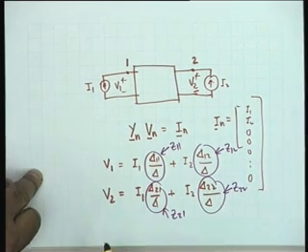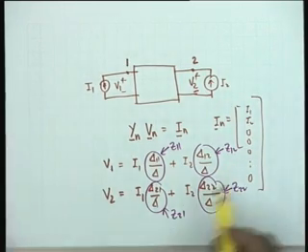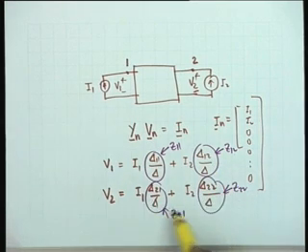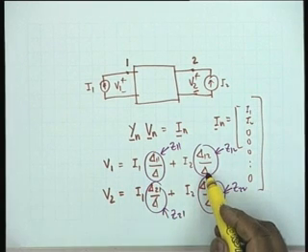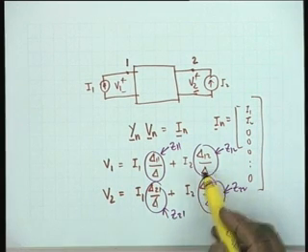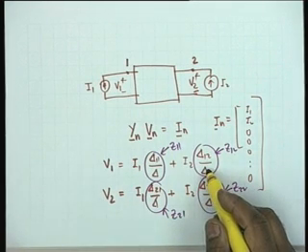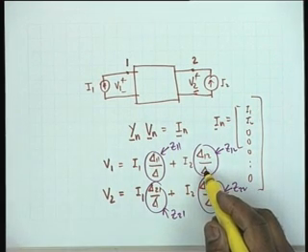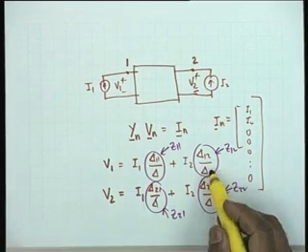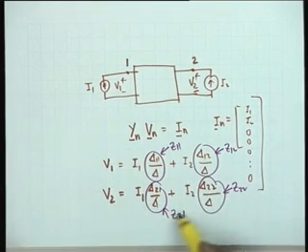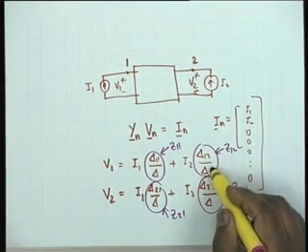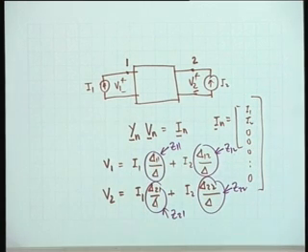And you see that poles of all the functions should normally be the same because the poles are created by putting del equal to 0. Any value of s at which del equal to 0 is a pole. This pole should be shared by all the 4 parameters. Any pole of Z12 must also belong to Z11.